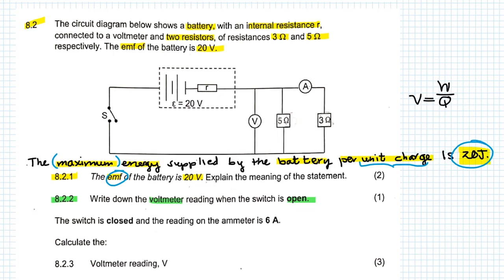So we take this side of the battery, we take the other side of the voltmeter and we draw backwards towards the battery, and we see that this side is connected to the negative terminal of the battery. If we go to the other side of the voltmeter, we see that as we draw the line backwards, we get to this point where we have the open switch. So it is not connected to the positive terminal of the battery. And therefore we know that the voltmeter reading is going to equal 0 volts.